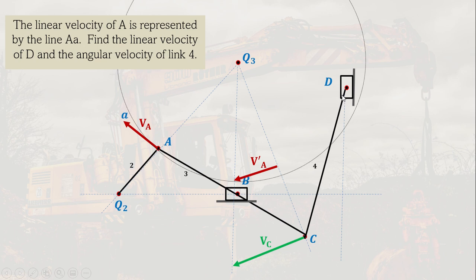So using again your knowledge on topic 4, you determine that there is an IC here connecting C and D. So there is a triangle again here connecting C, D, and this IC, Q4. So using this IC, we're going to use again another circle which has the radius of Q4C, since C is known. So we draw a circle with radius Q4C.